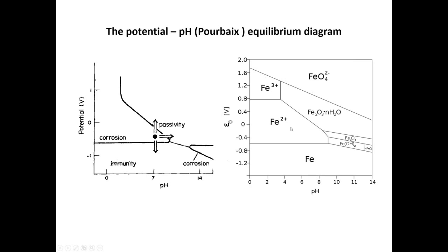So this one is an example of what we call a Pourbaix diagram that shows you the distribution of species of iron and its oxide at various pH conditions. So very clear here that under acidic condition, you have more corroded material, or in other words, low pH or acidic conditions tend to shift the potential such that you have higher corrosion rates or higher corroded material.